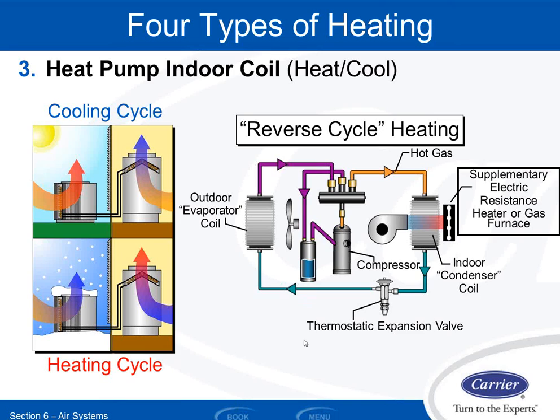Now, once again, that doesn't mean it's the least expensive. Natural gas is super inexpensive here in the Midwest. So if you have natural gas available, it's probably the least expensive way to heat your building or your house. Now, if you're on propane or oil or all electric, now a heat pump can really pay back because it's probably going to be the least expensive choice to you if natural gas is not available.